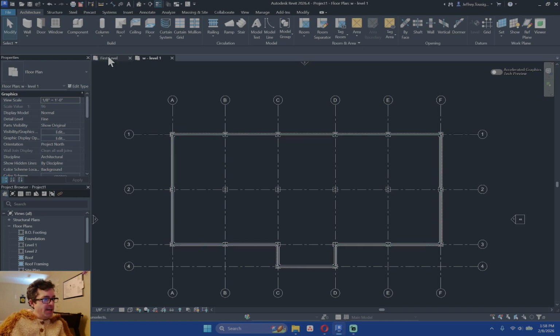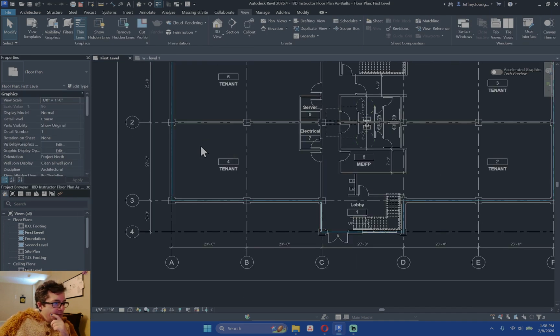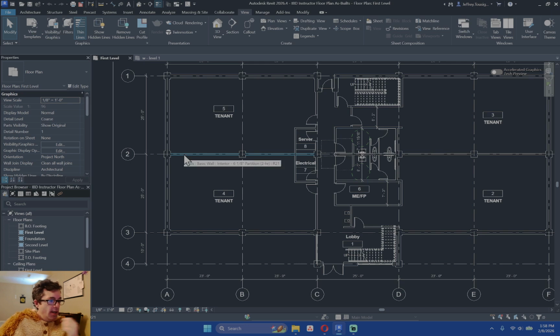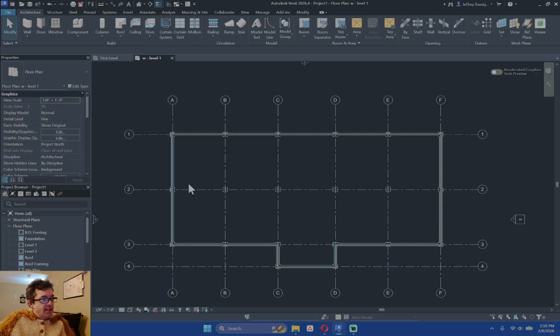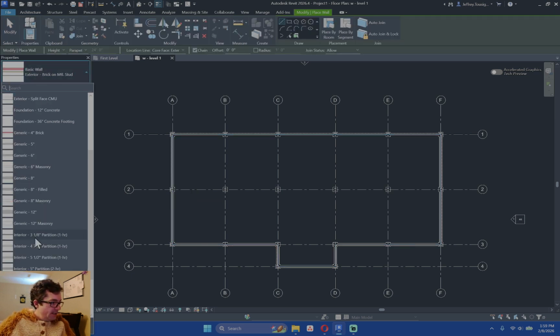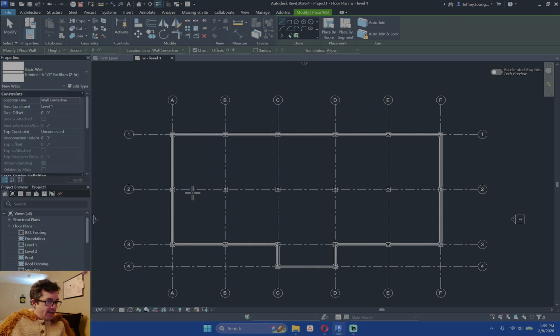Okay, now let's get to those demising walls. So going back in, I think I am just going to center line this partition between the spaces. Looks like suggested 6 and an 1/8 partition to our wall. We could do like a double gyp wall, double stud wall, soundproof acoustical. But again, advantage of this, if we center our walls, then when we change their size or their structure, it will just stay centered. So wall tool, interior walls. Here's that 6 and an 1/8. I'm going to go ahead and select that.